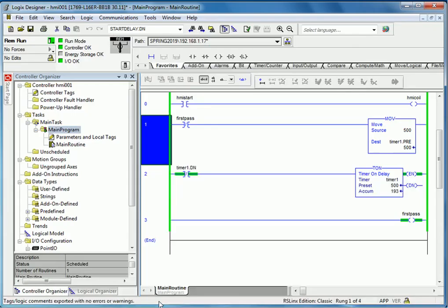So let's go back to the adder. I will go ahead and punch in a new time for the time delay, and we should see it update right here. So let me put in 250. And of course it changes, so now I have a 250 millisecond timer that restarts by itself.